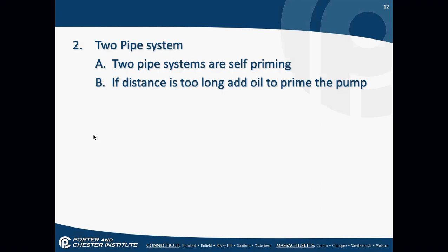What's going to shut it off? The primary control, right? It's going to trip on the primary control. There's no flame. I have no oil.